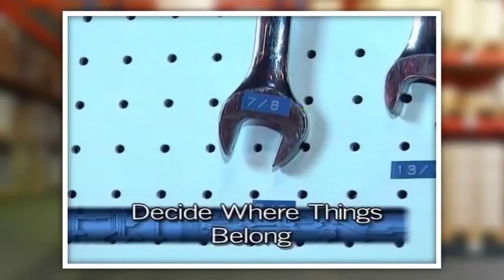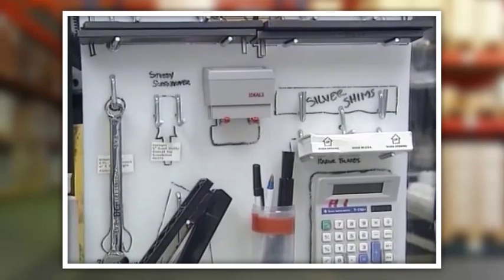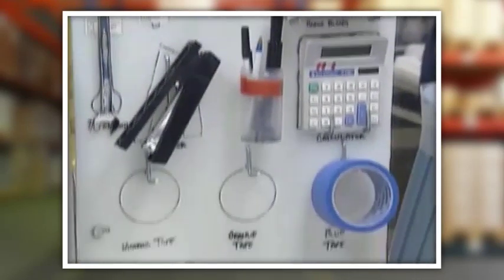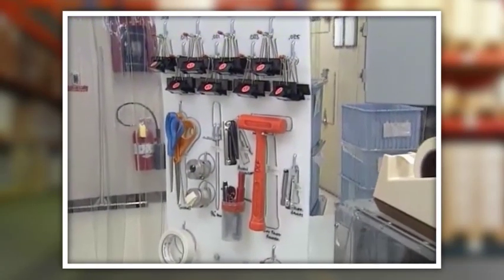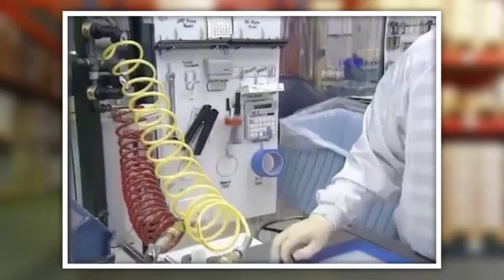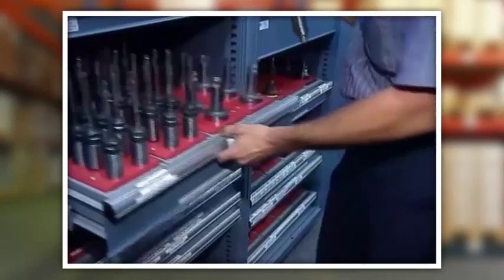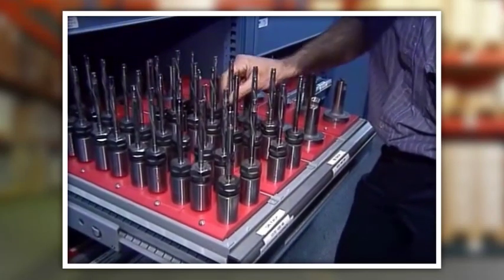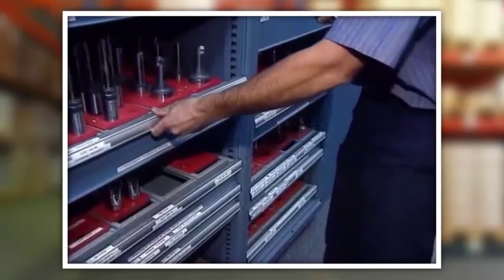Step 3. Decide where things belong and how they should be kept, and put them there. There are 4 guidelines for determining where and how items should be located. The more often an item is used, the closer it should be to where it is used. Every item should have a designated location and should be labeled with that location. The label may even specify the shelf or drawer where the item belongs. The location should also be labeled so that it's clear where the item should go.